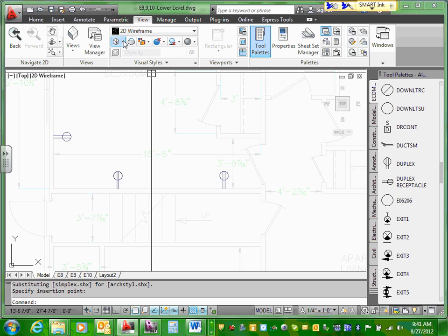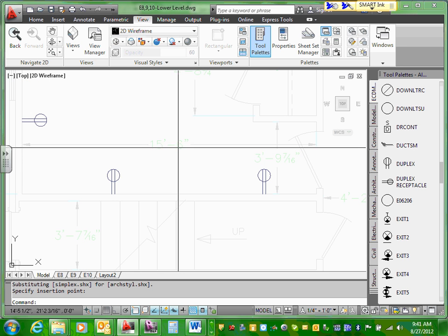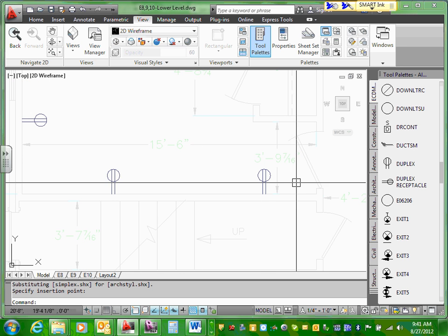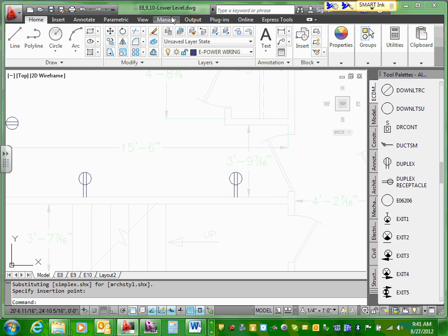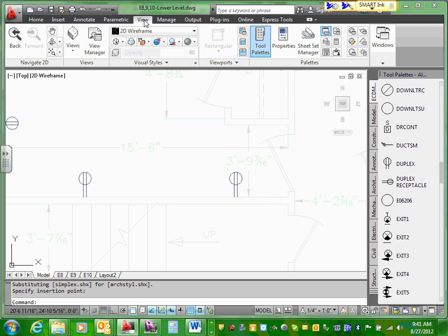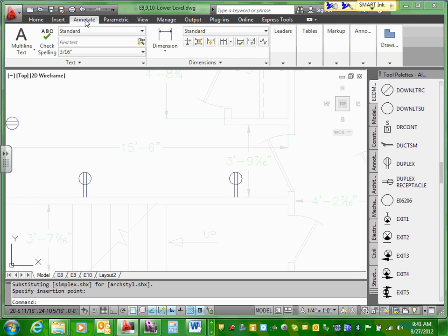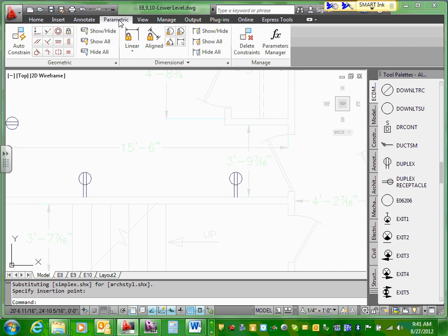Now, how do you know when you lay them out? Can you guys see the distance here, 15? Remember the rule that we lay out. If you go to the home view, which one gives you the measurement? Annotate, not dimension, that ruler.